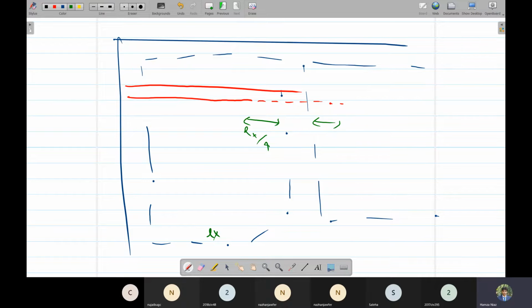So bent up saves our steel because one bar is going as positive in the bottom, then it changes into negative for the same slab, and again negative steel for the other slab. So this is saving our steel, but it is difficult to provide in actual conditions because we have to bend all the bars.